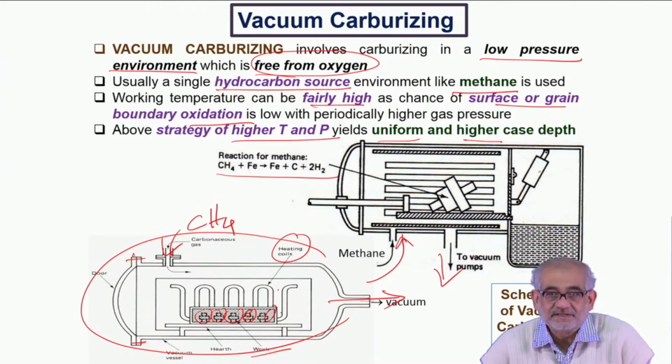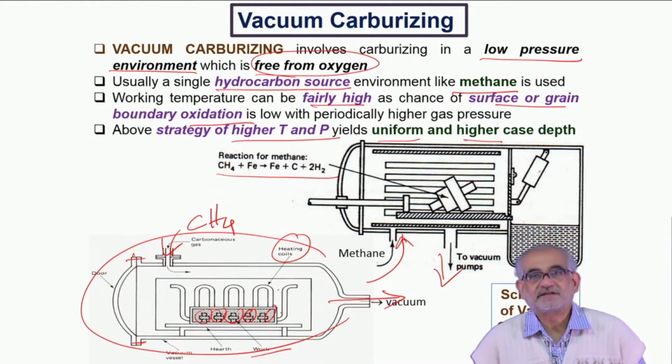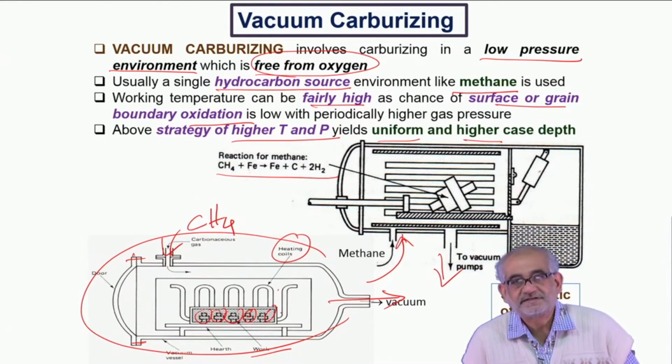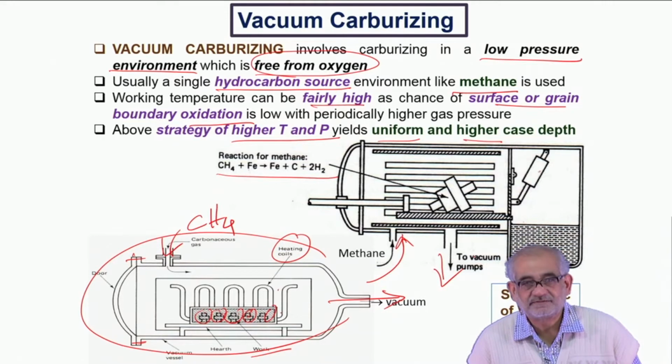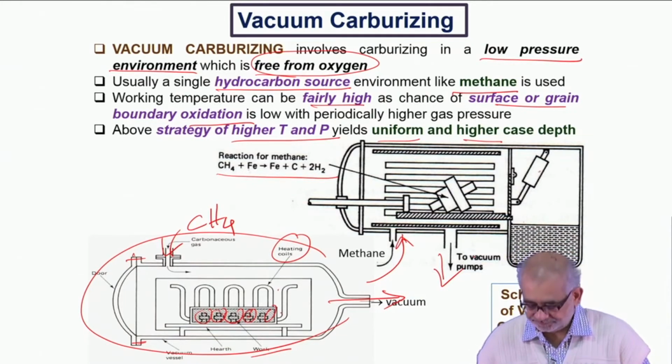And this is done by a so-called thermochemical process, by way of introducing carbon onto the surface. And very soon we'll discuss the subsequent heat treatment that is given, and that would amply explain the creation of this graded microstructure, which also creates a challenge in terms of heat treatment of the stock after carburizing, so that we develop very high hardness and wear resistance on the surface, but maintain high toughness at the core.